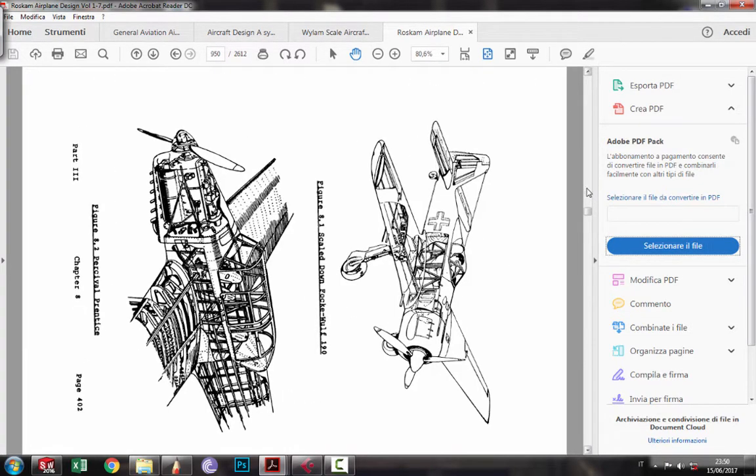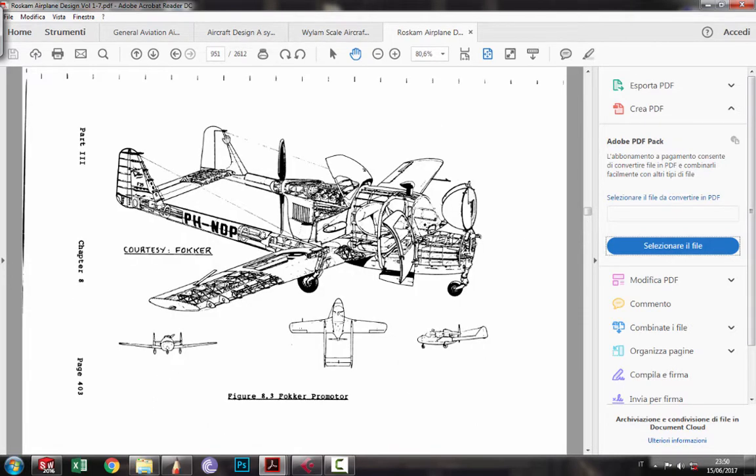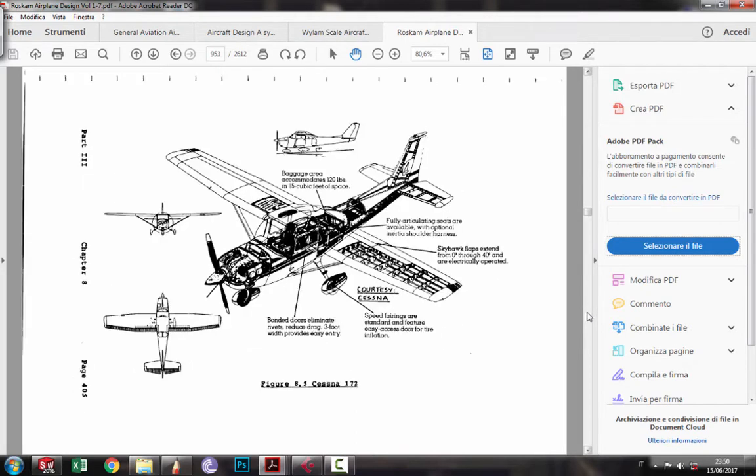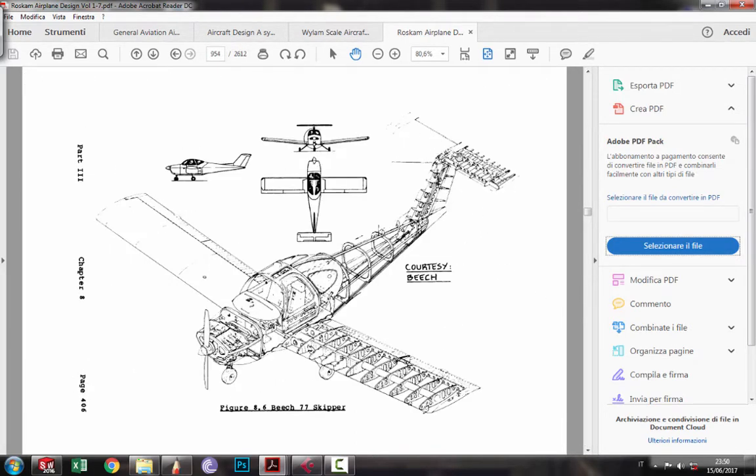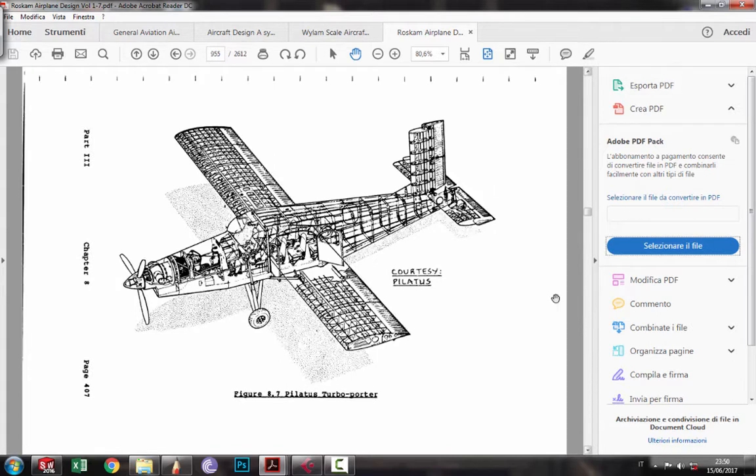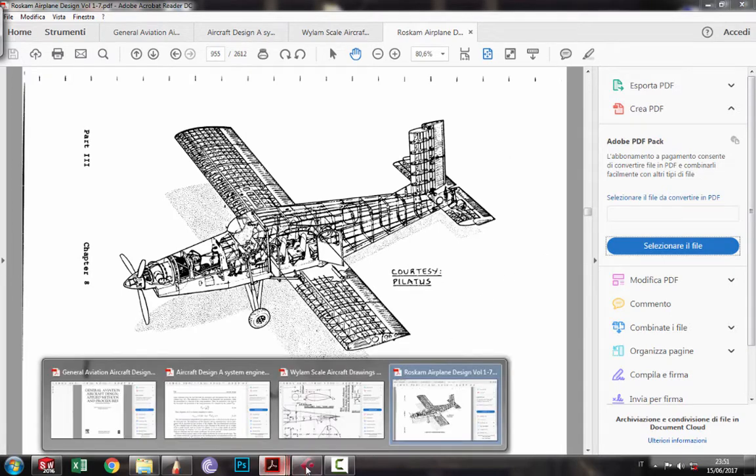I will show you, for example, with this type of wing of tail, the propeller is in pusher configuration, not tractor. The tail, T tail, and also just take a look at how it's built. We can see here that for the Pilatus we don't have anything. We don't have tapering. We have the same profile from root to tip, without sweep angle, no taper angle, no twisting, nothing.